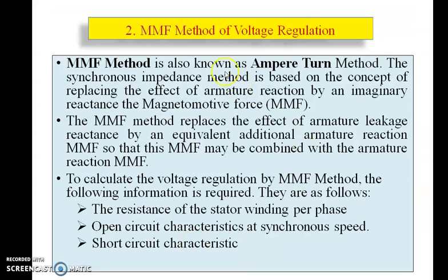Now we will move to the second part, which is called the MMF method of voltage regulation. MMF method is also known as the ampere turn method. The synchronous impedance method is based on the concept of replacing the effect of armature reaction by an imaginary reactance to the magnetic motive force MMF. The MMF method replaces the effect of armature leakage reactance by